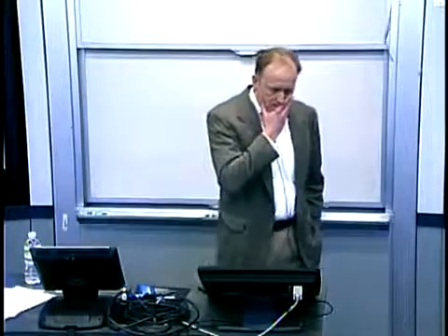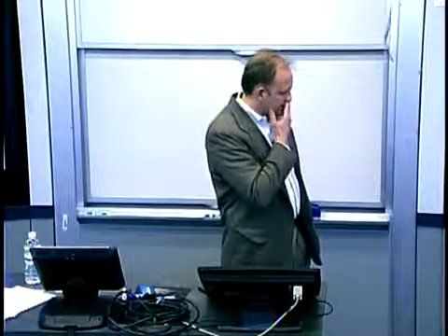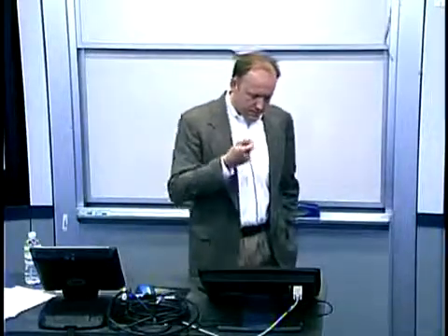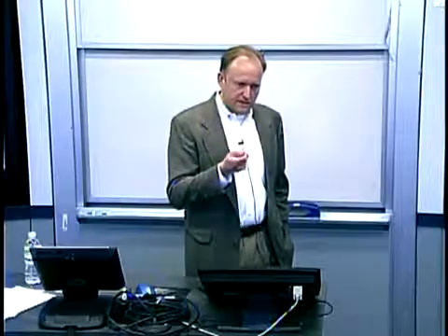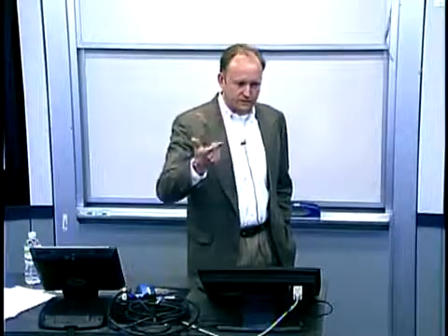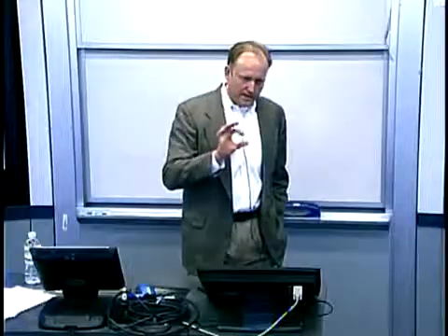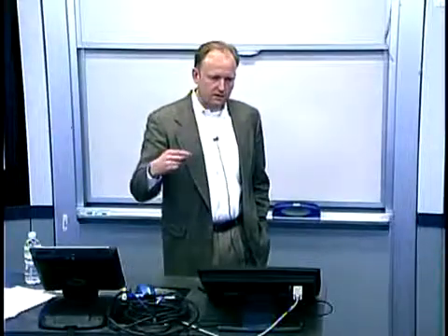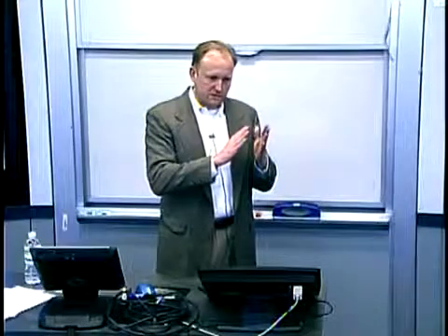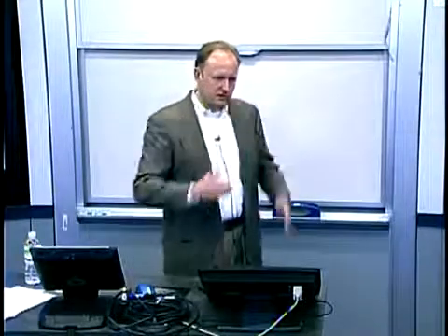Yes? Why is it saying smaller the better on the y-axis? Yeah, so smaller the better is the parameter of interest, meant to be smaller is better. But then when you compute a signal-to-noise ratio, larger is better. So the underlying parameter, called A20 in this case, smaller was better. But in Taguchi's methodology, you then take that parameter and its variation and transform it to get a signal-to-noise ratio. And with signal-to-noise ratio, larger is always better. So I appreciate why that's confusing.